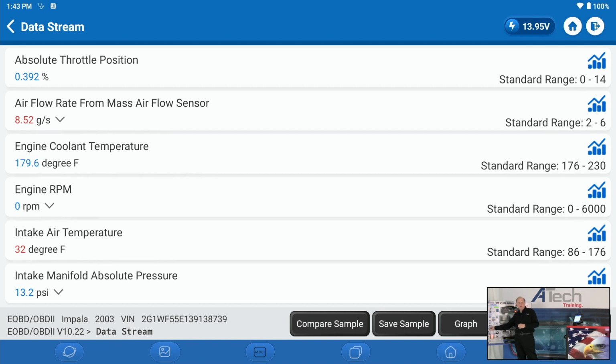No, it didn't do anything at all. So we're looking at it, but it did some other things. All right, it did change. It went down to, if you look at 69.8, if I turn this thing up a little bit, I'm at a different temperature. So when you first start up the vehicle, you want to make sure the temperature of the coolant temp sensor and the inlet air temp sensor match. So right now I got 69 and 32.